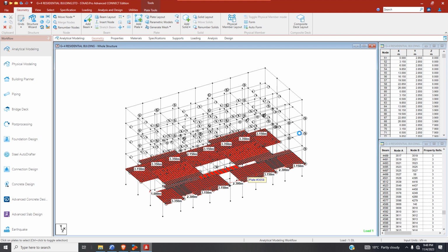Just a straight line. So I just add, define rectangle 0.3 by 0.2 and add, then select by using property and assign elements. And I go to view all structure and I'm going to preview. That's how the structure will look like.